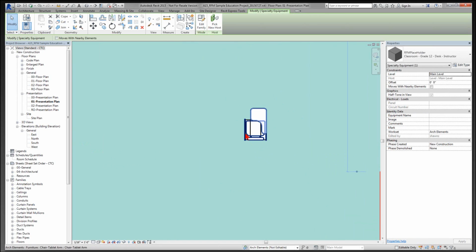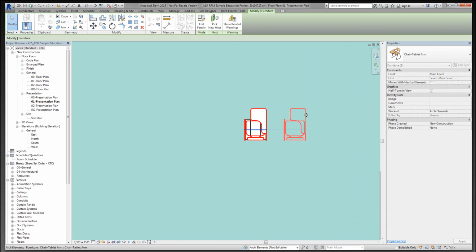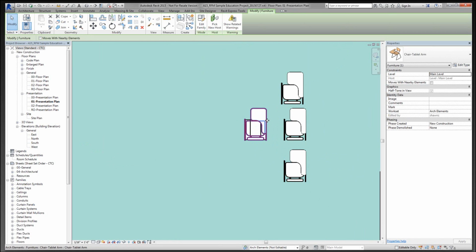As I pull this off to the side, one of the things you'll notice is that I have some components out here that are not generic components. They look better defined than just a cube. These are those tablet desks that I placed out there. So I can move these around and spatially plan out what I want these to do. Of course, I can grab them and rotate them, simple space bar actions out there. Can rotate these components, putting them wherever I'd like them to go, right?